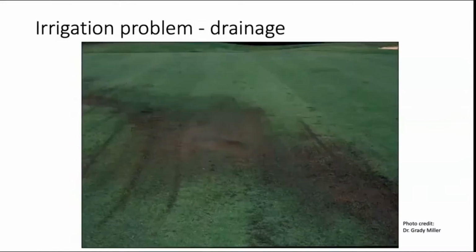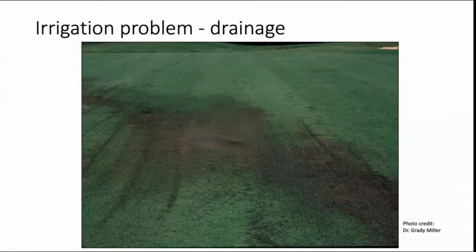It also promotes disease. Drainage. So all the things when you're doing an audit, and even when you're operating the system during the audit or afterwards, you want to look for things on the ground that tell you you're putting on too much water, or your field isn't correctly graded, or you have drainage issues.